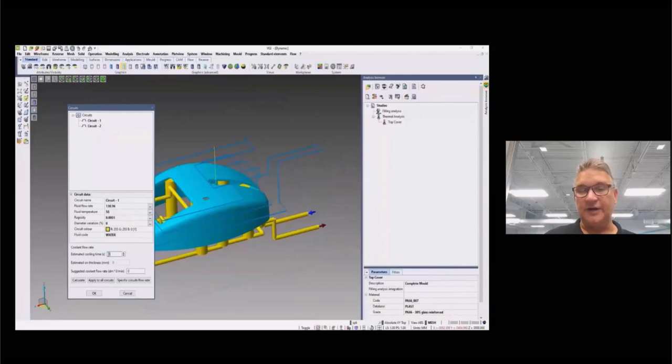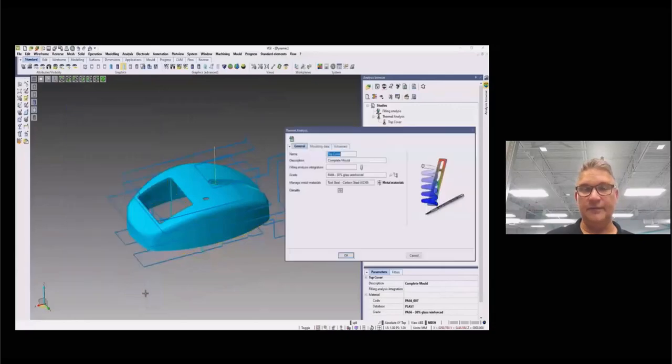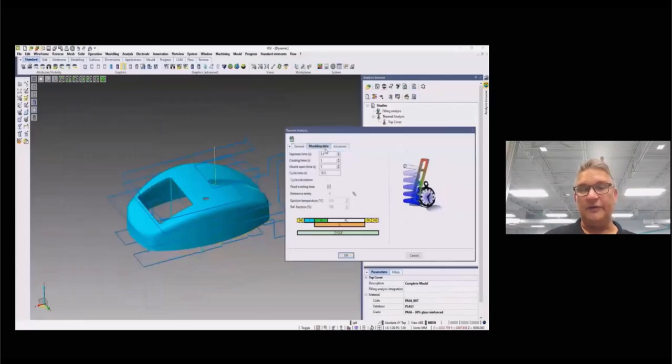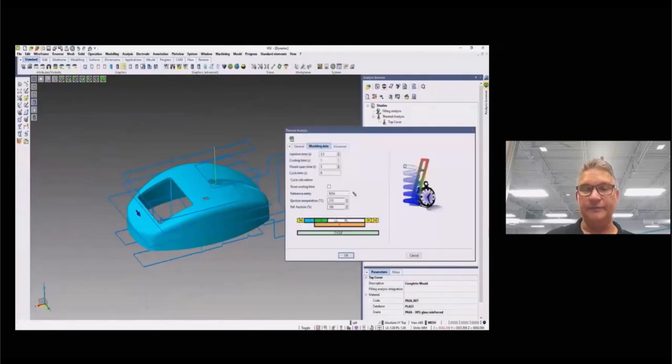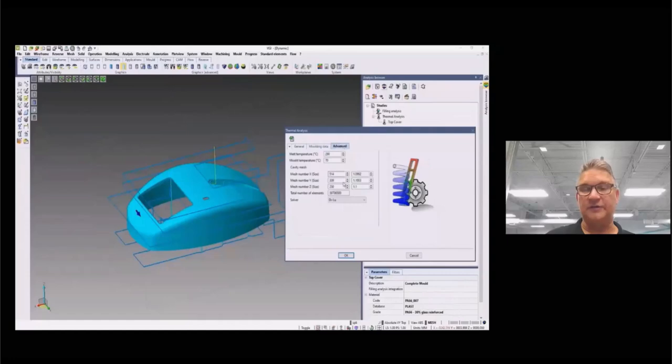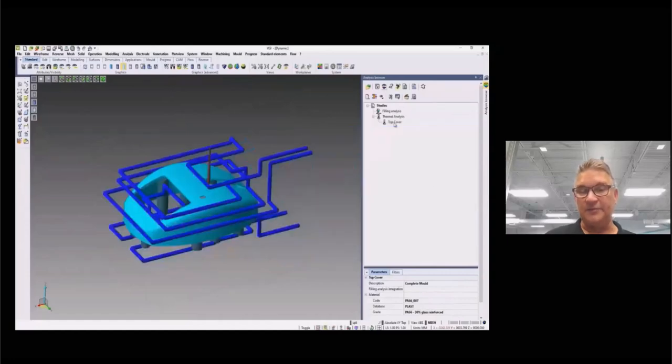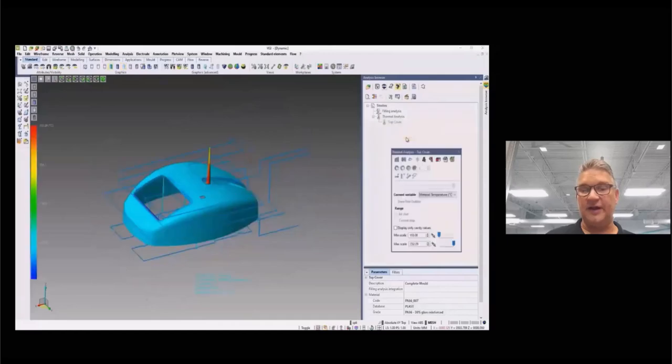The calculation of the cycle can be set based on experience or left to the software in reference to the cooling of the desired area of the piece. Upon reviewing more parameters under the molding data tab, we can set the cooling time to a fixed value by clicking on an element on the model. Note that the block containing the inserts and the cooling circuits can be meshed up to 40 million triangles. This provides very detailed, sophisticated analysis.